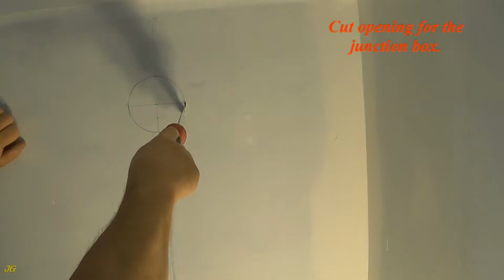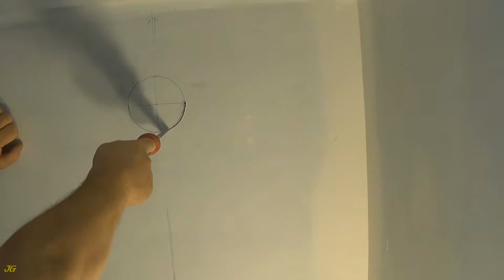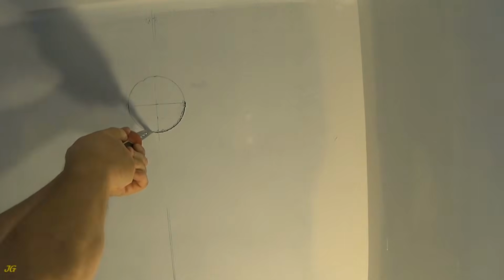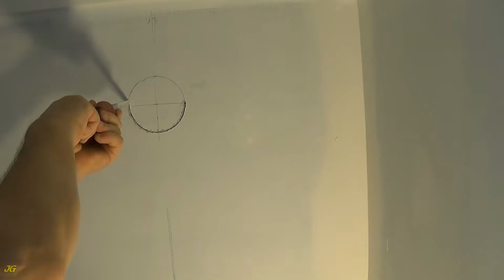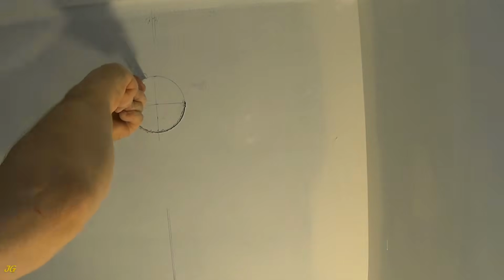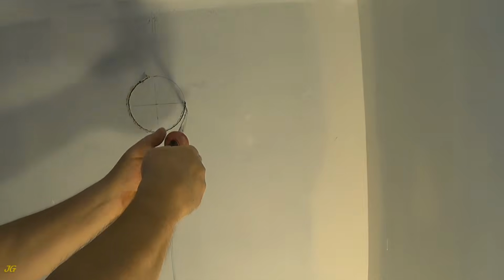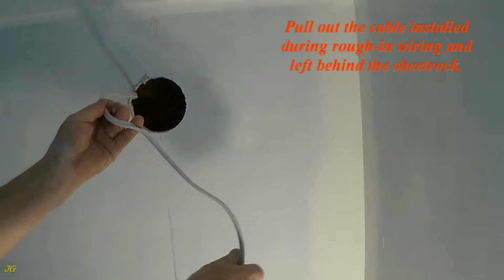Cut the opening for the junction box. Pull out the cable installed during rough-in wiring and left behind the sheetrock.